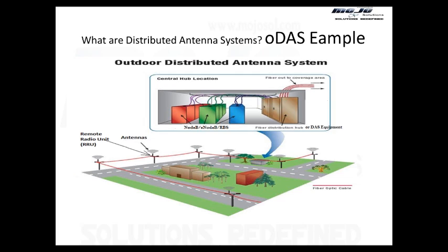If we have overlapping coverage, it will increase the handover. So coverage is designed in a way that the cell is dominant. The cell which is intended to cover a given area is dominant in that area, and it's not dominant in another area, and that is the whole purpose of our design. If we have overlapping coverage, that creates pilot pollution.